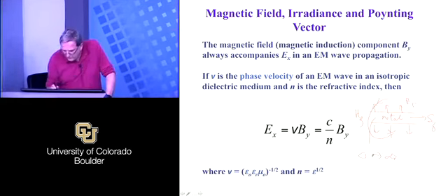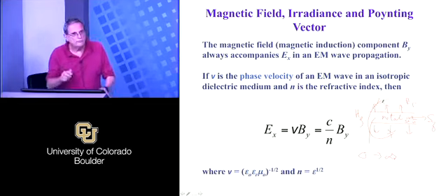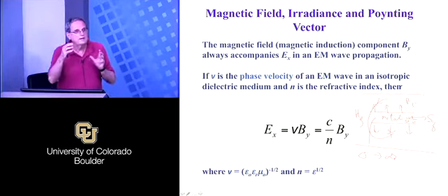But anyway, as Heaviside told his boss, look, the sigma is really big, and that means that the charges inside of here can move around quite freely. So there isn't going to be any electric field inside the metal. There won't be any magnetic field inside the metal. It's going to be about zero. However, near the edges, you'll have really strong field. It'll be pointing up. So it was this model that Heaviside used, and he told his boss, look, don't spend money on the metal, spend money on the cladding material, spend money on the metal coating.